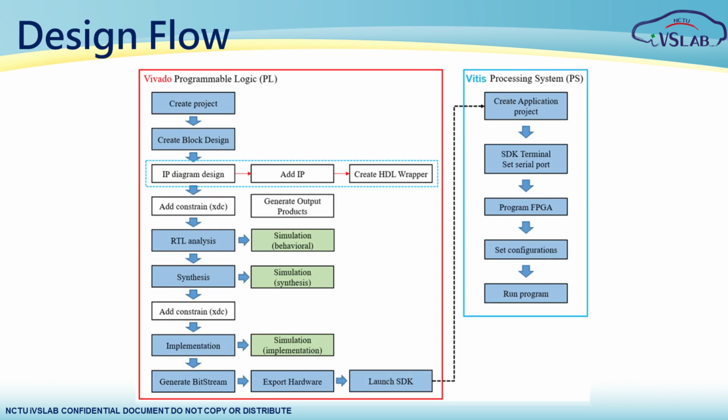Our workflow is divided into 2 major parts. During the Vivado phase, we will configure the block design, run design validation, and generate the bitstream. The most critical step here is to export hardware to generate an XSA file. This file encapsulates all hardware configurations and address mapping information, serving as the absolute foundation for our subsequent software development.